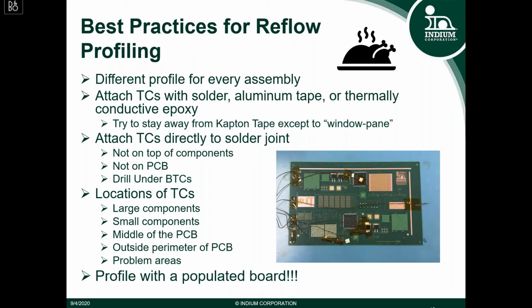Dummy components are available, but it will be absolutely worth it in the long run and in the quality of the solder joint or quality of the whole assembly in general if you profile with the populated board and get accurate readings. If you're a contract manufacturer, make sure that your customer understands the importance of profiling with a populated board and how it's going to affect the overall quality of the product that they're getting.